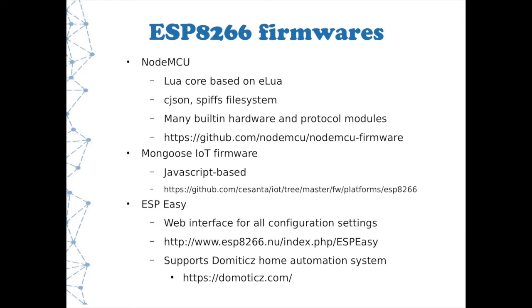These are growing too. NodeMCU, like I talked about, is a Lua scripting language-based firmware. I've recently found this Mongoose firmware, and it's JavaScript-based. So if you want to write your application in all JavaScript, you've got a firmware available. ESP Easy is interesting because it has a web interface built in that lets you select and control things on your chip, so there can be less programming involved and more clicks through a web interface. So that's an interesting one.